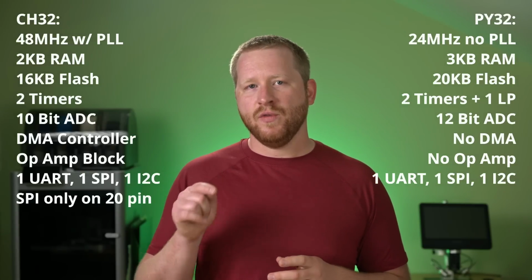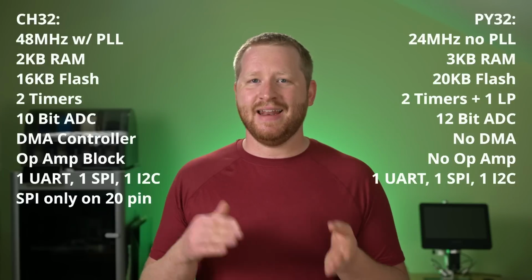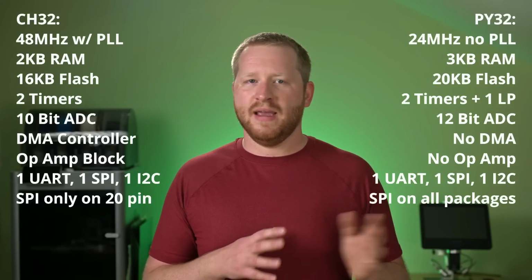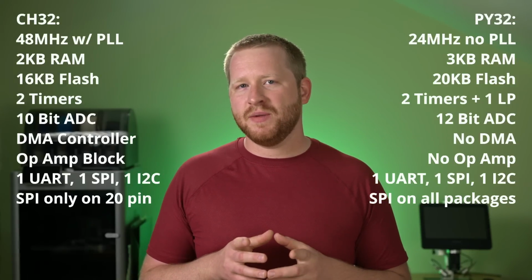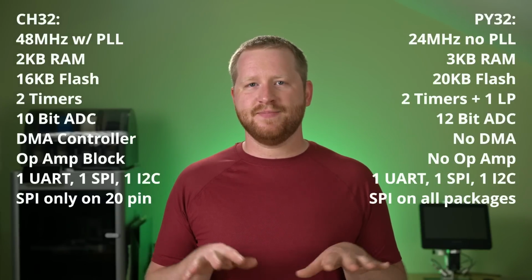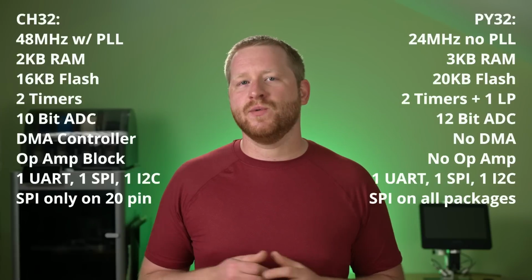The SPI is only broken out on the 20-pin packages. There's no SPI on the 16 and 8-pin options. Compare that to the PY32, where you get the option for all 3 regardless of package. If you have an application in mind though, you should probably check out the multiplexing on those really small packages, as some of those functions overlap. Other than that, these 2 parts are really similar.